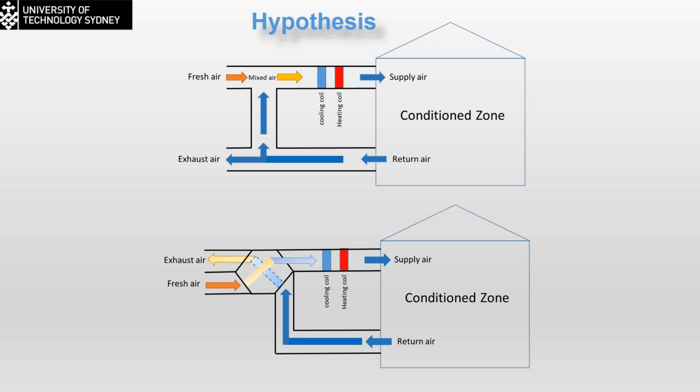So this is a comparison between the two cases, and actually we should go for this one using the indirect cooler as a 100% standard free-cooling system, because you know that the days in Australia so far, the temperature outside is quite good. We only have to treat the air a little bit lower and send it to the zone, and thus we don't need to use the vapor compression system in most of the cases.